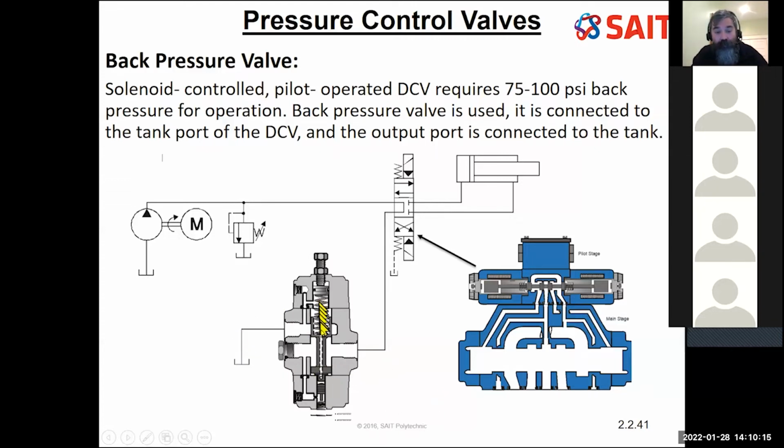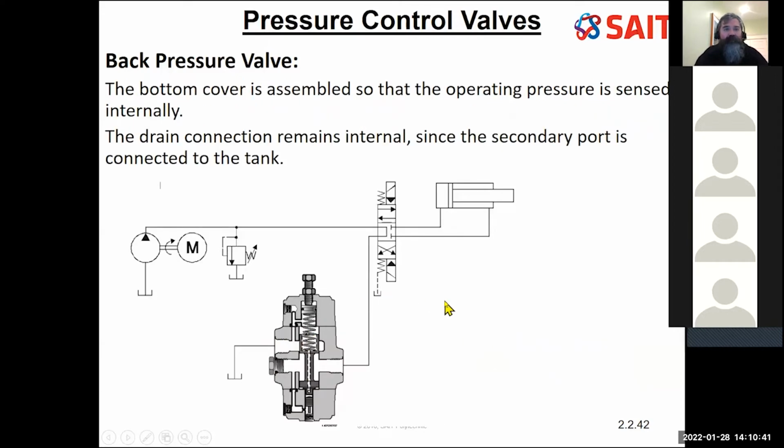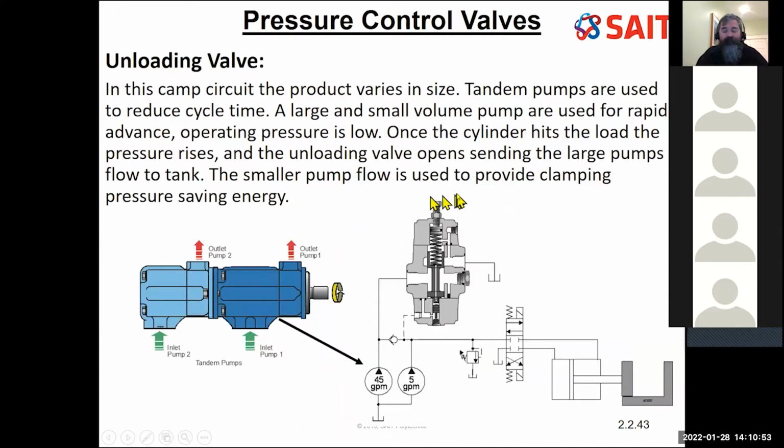So it's going to open based on the spring force, whatever I set that to, and allow it to open and run. Pretty much the same as the pressure concept we were talking about for our pressure relief valve that we first talked about. More surface area, add pressure, it opens, lets fluid go. Not a biggie. This is just talking about the way it's assembled and the way that pilot works in order to operate the valve.